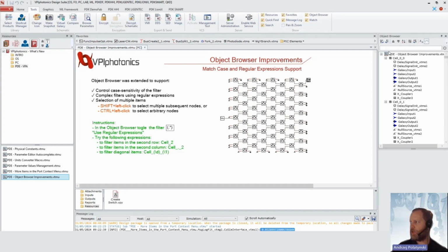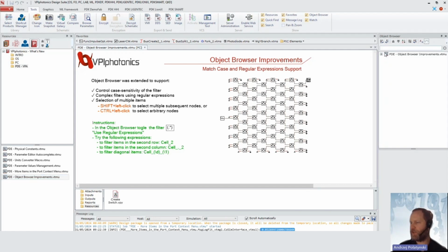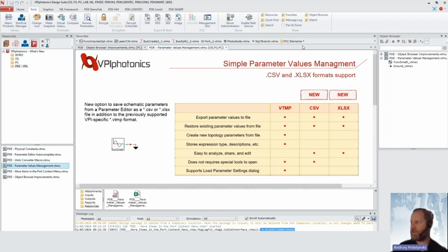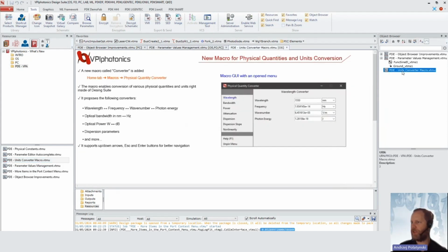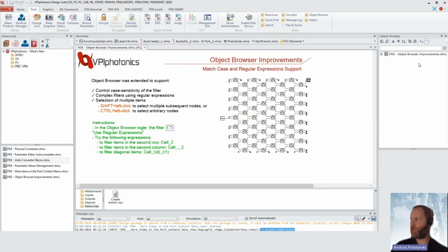Within the Object Browser, you will mainly have access to the information from all the parameters and all the schematics that are open. So let's imagine we are opening another schematic. You can see that the schematic appears. The more schematics we open, the more we will see them directly. But let me come back now to a single schematic to show you what the interesting features are there.